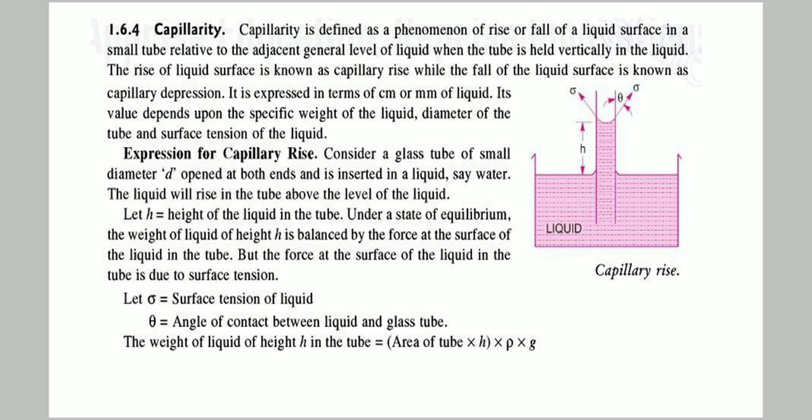Next is capillarity. So capillarity is the phenomena of rise or fall of a liquid surface in a small tube relative to the adjacent general level of a liquid when the tube is held vertically in the liquid. So suppose we are taking a small glass tube and dipping it inside a beaker of water.